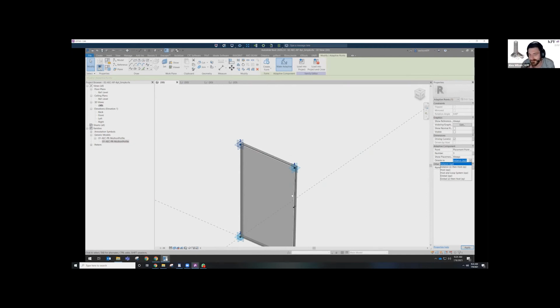However, these are pretty problematic, which is why in a further example, we start to remove these and control the back face of the panel by using additional points. We found that if you can control the placement of the points, that is very stable. The relationship of the geometry between the points is also extremely stable. So we started to strip away some of the automatic things built into Revit to just control it ourselves. Well, parametrically, not manually, because we just found the risk of inconsistency in Revit's performance and variation is too high. That's a very diplomatic way of saying what everyone knows I was trying to say.